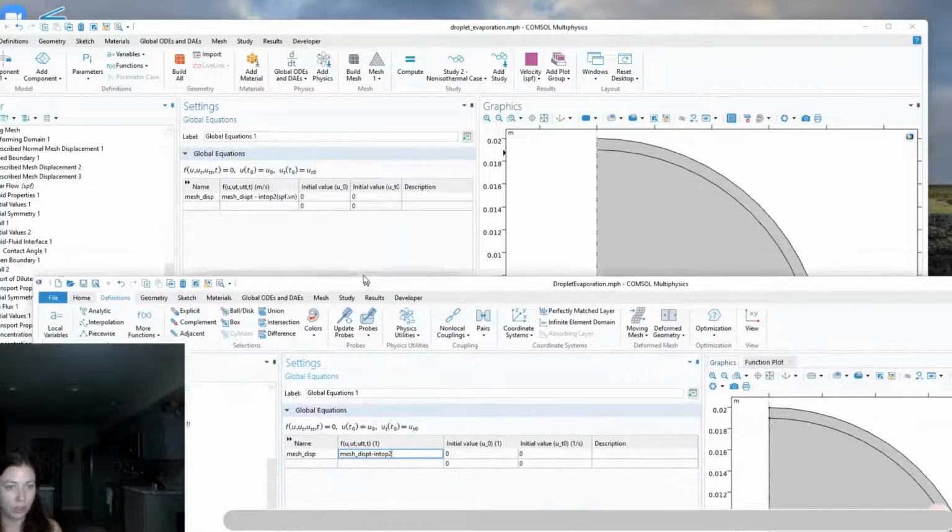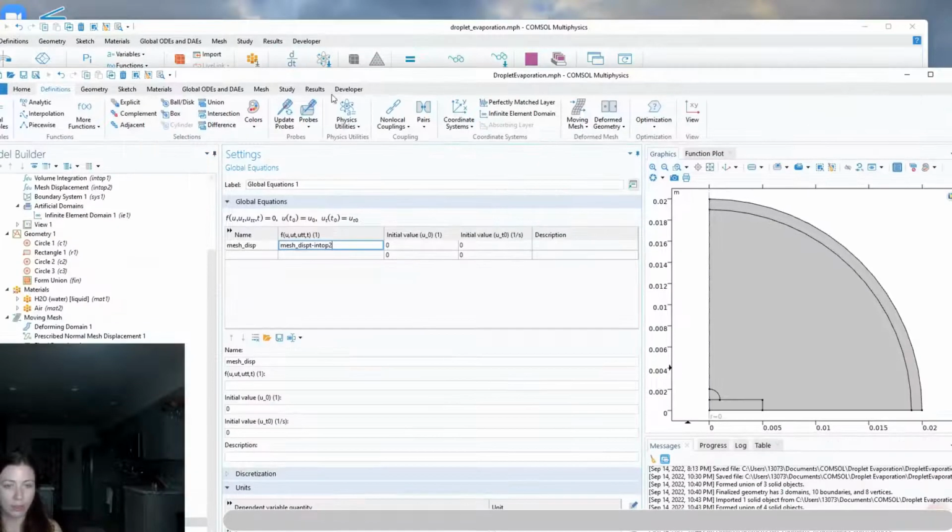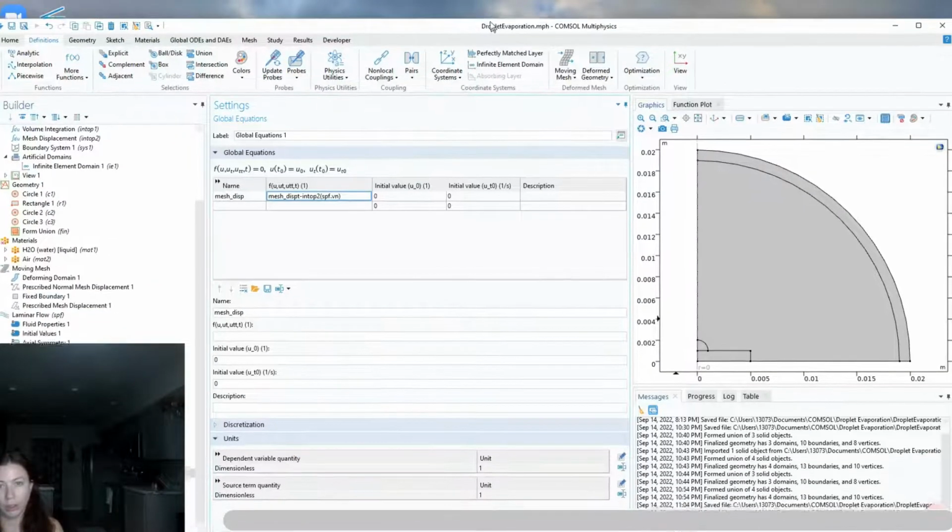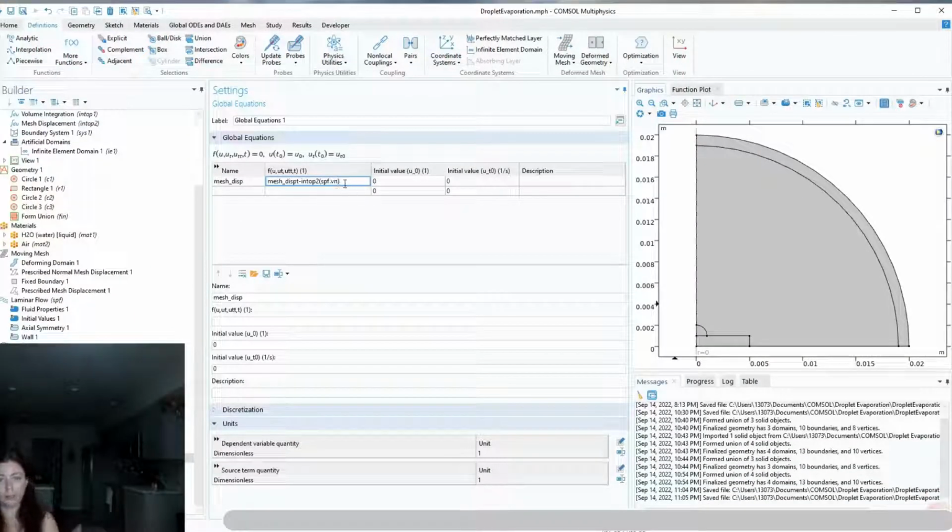And as a function of spf.Vn, single phase flow output Vn. So V is, remember our velocity, U, V, and W are the letters that correspond to each of the coordinates, and since we're using polar coordinates, our second coordinate would be phi. So in polar, it's R, phi, Z. So since V corresponds to the second coordinate, this would be the phi, basically the normal velocity,